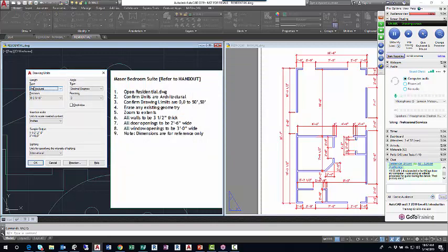The units are architectural. Angle type is decimal degrees, that's fine. The precision is 1/16 for the length type, which I like. It probably could be less precise. I don't like it to be as high as that 1/256 of an inch. I think that is excessive. They won't have a real need to be that high. And then precision on angle is 0, that's fine. Insertion scale is inches, that's fine.